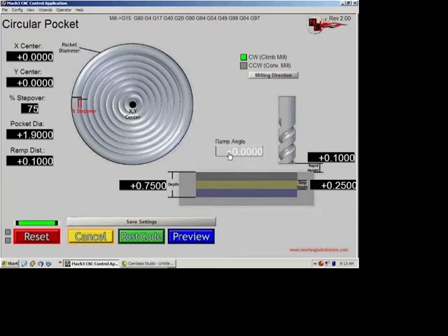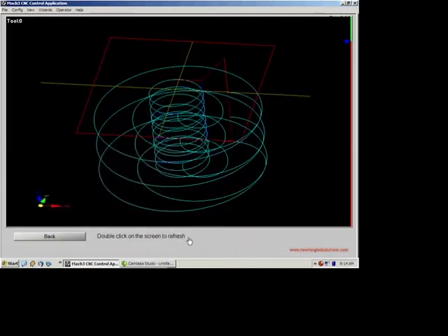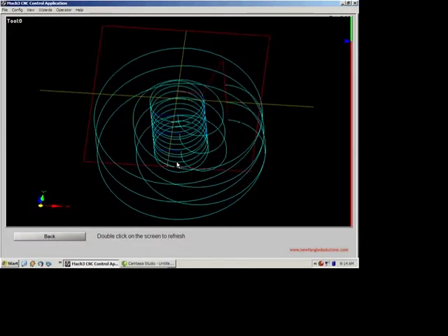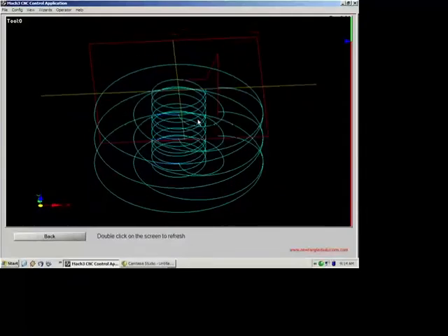That's why we added this DRO here. If we typed in 3 degrees, try that again, for a carbide tool or even high-speed steel end mills, non-center cutting end mills can now cut blind pockets. They're a little bit cheaper, easier to regrind for the home type user, or indexable inserts because there's nothing in the center of the tool to actually cut with. If we hit preview, we can see that we now have a helix going right down the center of it.